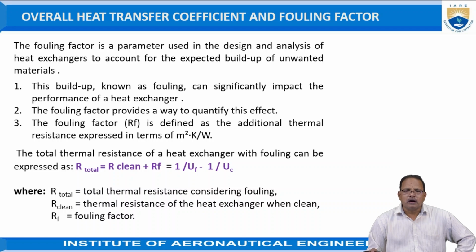Hence, according to the manual, some regular maintenance is required. It may depend upon the number of hours it is working and the type of materials used in the construction. But in between, because of scale forming, even though we remove the scaling at regular intervals, the effect on heat transfer due to the fouling factor has to be considered while designing heat exchangers.